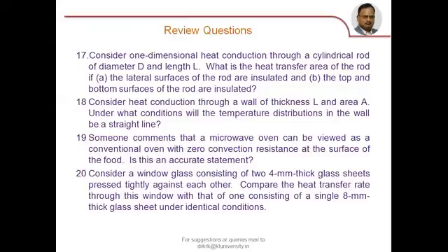Already 16 review questions are presented in the last sessions, and the answers are also given in the previous sessions. Now let us take a look at the questions from 17 to 26. Mostly all these questions are based on conceptual understanding. So consider a one-dimensional heat conduction through a cylindrical rod. What is the heat transfer area we have to consider if the lateral surfaces of the rod are insulated, and if the top and bottom surface of the rod are insulated?